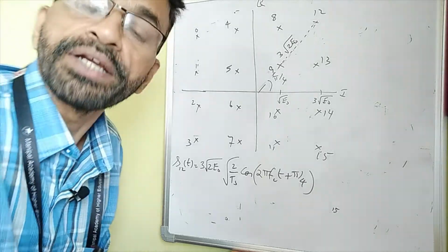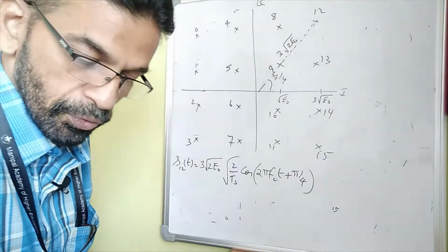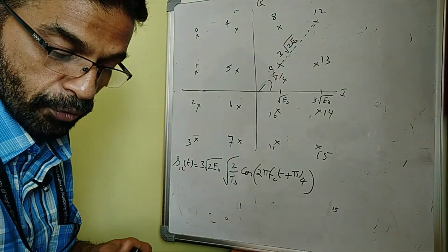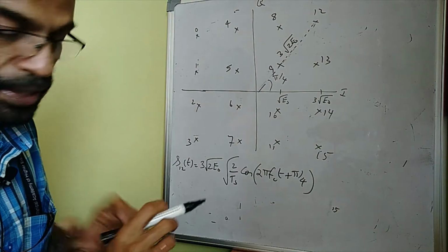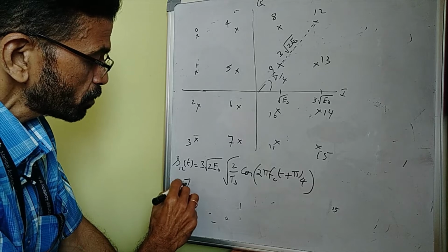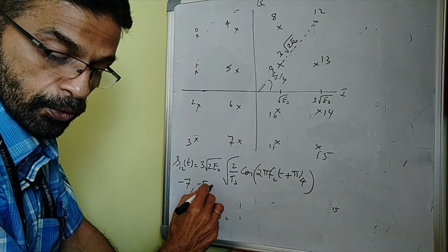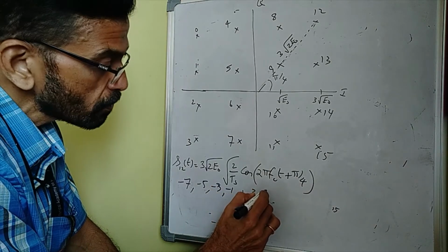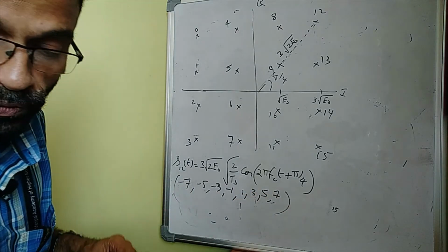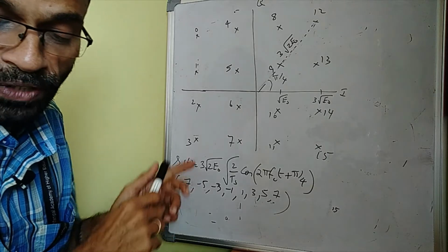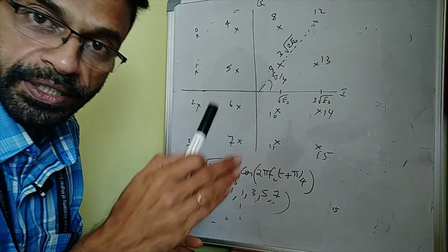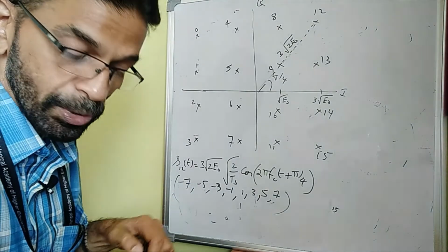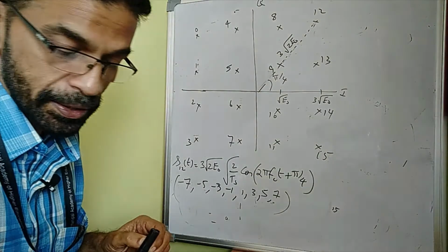So that's the point. And of course, one thing before I move on, we can also have 64 QAM and 256 QAM. So in 64 QAM, you will have the di and dq taking values -7, -5, -3, you can verify this later, -3, -1, 1, 3, 5, 7. And in 256 QAM, you will have values from -15, -13, -11 till 11, 13, 15. And 64 QAM and 256 QAM are used in cable modem and digital cable TV.